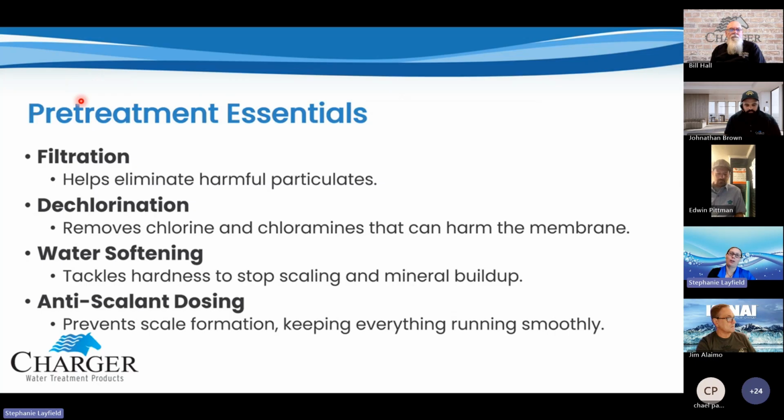Pre-treatment essentials are very similar to our residential RO. Filtration, of course, is going to reduce that silt and those colloidals. Dechlorination: all of our membranes nowadays are TFC, so they will essentially burn with any oxidants in there. Water softening or anti-scalant dosing,